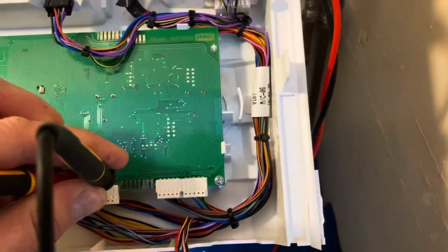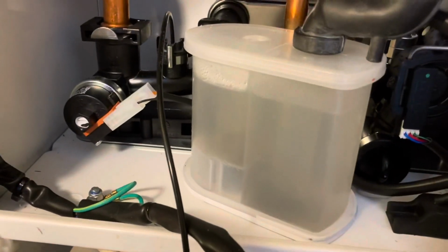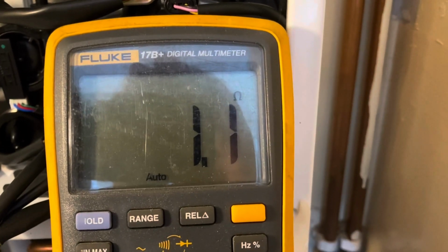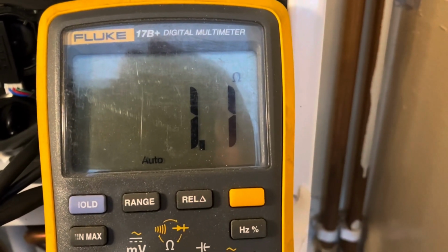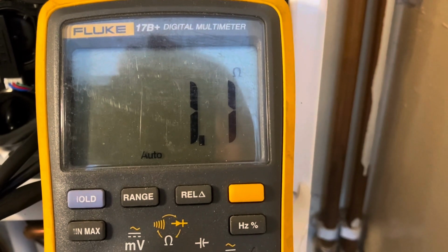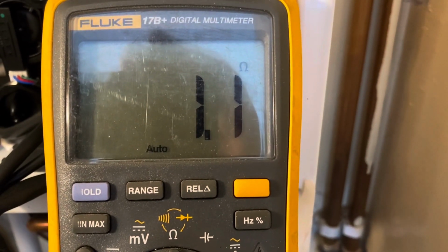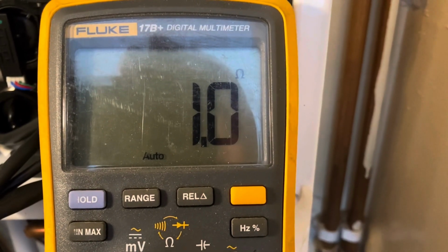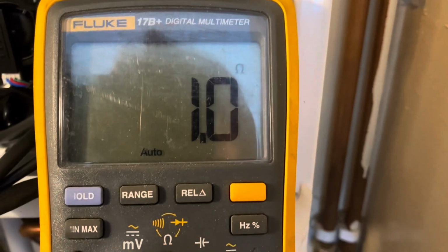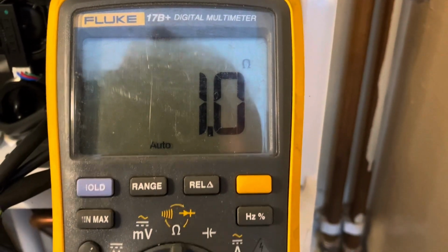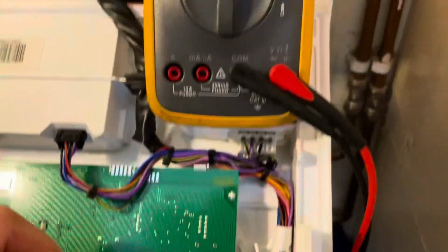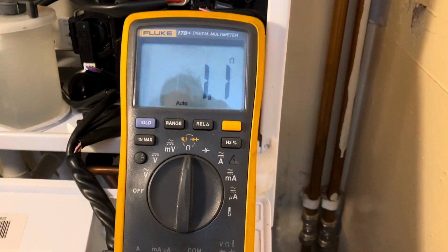There you go. I'm on it. I'm testing the low water pressure switch now on the black and orange, and I'm getting 1.1 ohms. So that tells me that switch is in the closed position, which means it's working. So it's letting an ohm through it, which is a good circuit. If that switch was open and the pressure had dropped, you'd be getting mega ohms on that switch. So I know that switch is okay and working, and we should have enough pressure in the boiler. So that's the thermistors and the low water pressure switch done.